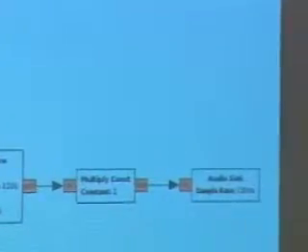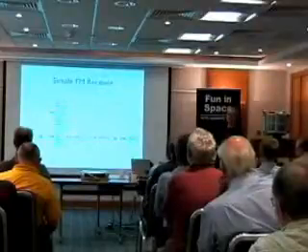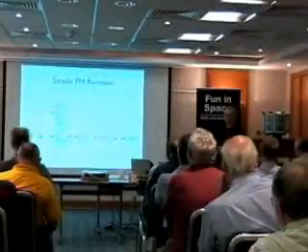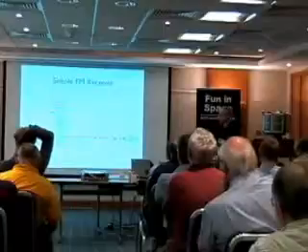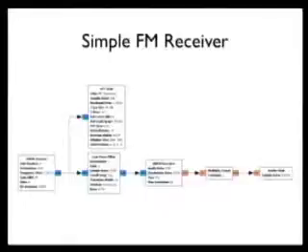On the left side, there's a USRP source, which is the interface to the hardware. It's like a driver. It gives you the data stream from the hardware. There is one arrow going up to an FFT, which is a must in software radios. It will simply display a spectrum display, and if you don't have that, then I don't think you can call it a software radio. You need some graphical fanciness, right? And so it will show the raw spectrum.